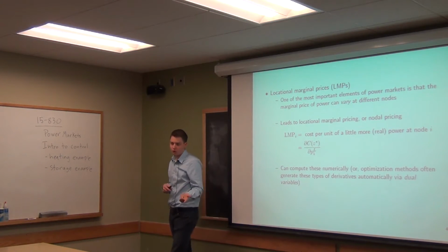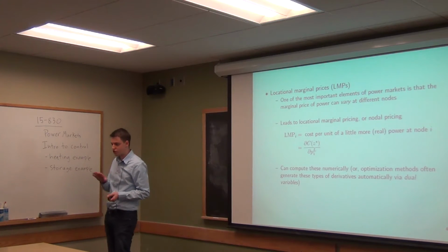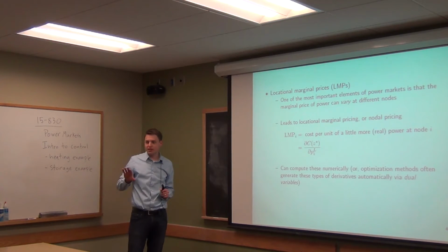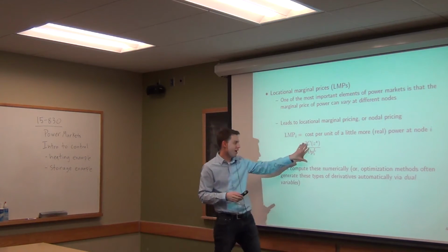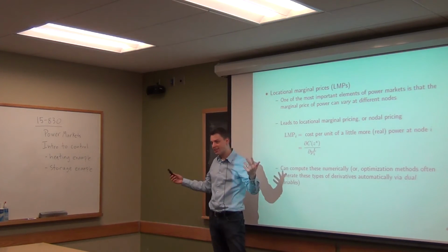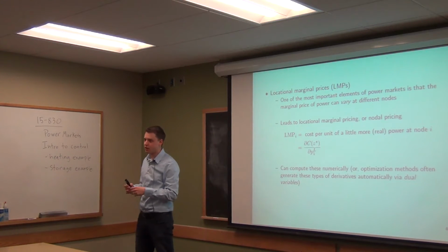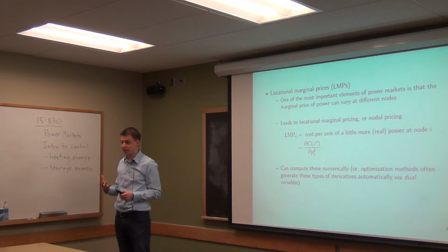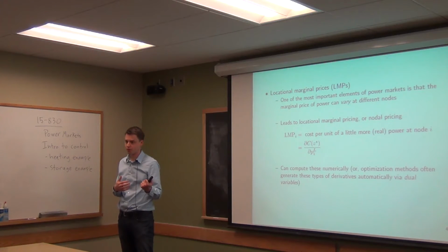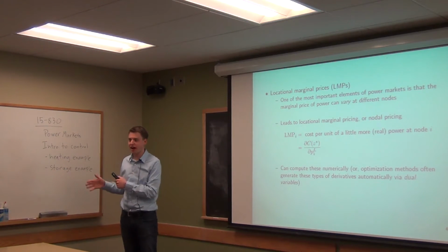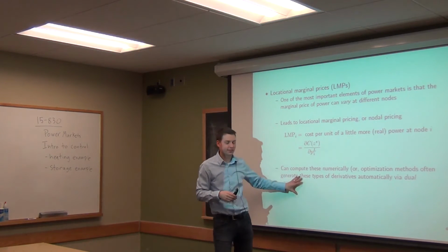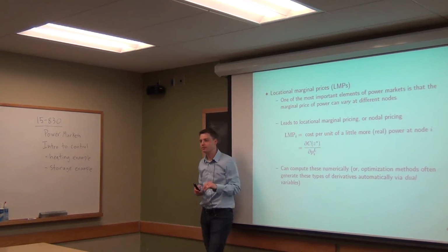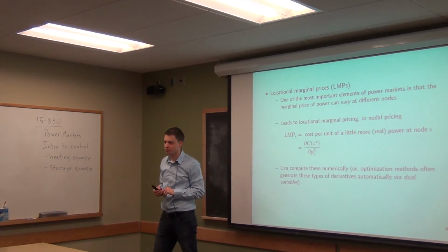We're not going to go through how that works, but you should know that to compute LMPs, they are in fact not running this optimal power flow problem n times for the number of different buses they have. You can just solve it once, and you get a lot of these things for free when you solve the actual optimization problem. Just as an aside, that's how it's done in practice. It's not done exhaustively with numerical derivatives.